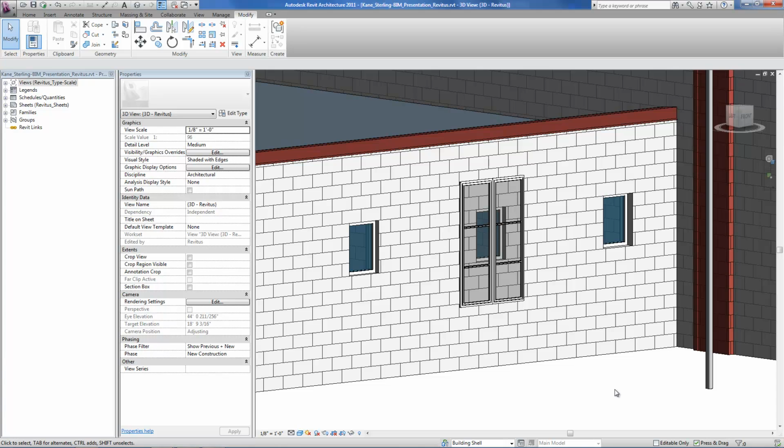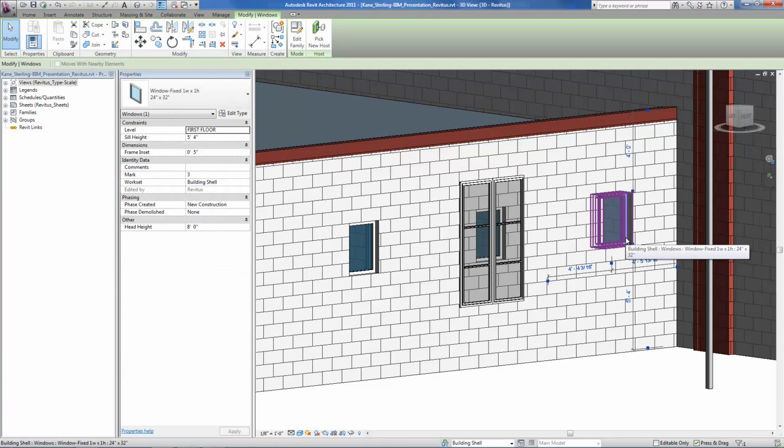Also, notice that the window style is a single panel unit with no dissecting mullions. To match the window, we will want to turn off the horizontal braces and eliminate the vertical mullion. Based on the rules and functionality of the security screen family, you will see that much of this will happen automatically when we adjust the size.